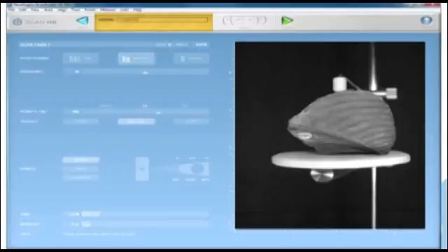And then on the left, you can set at the top left whether you're going to do a full 360-degree scan, or just a single scan, or a bracket scan, which is a case where you do a scan of one particular direction, and then you go either side and do a scan to give you a better 3D cover.